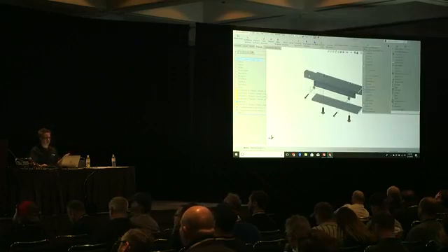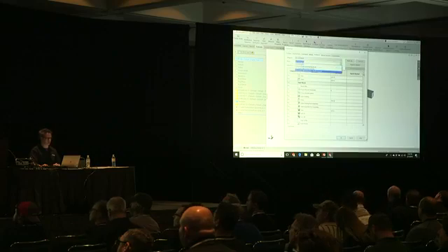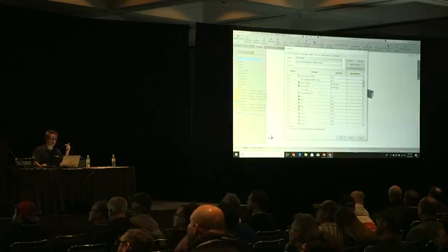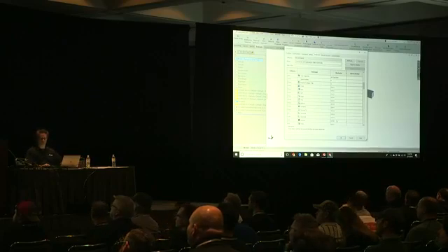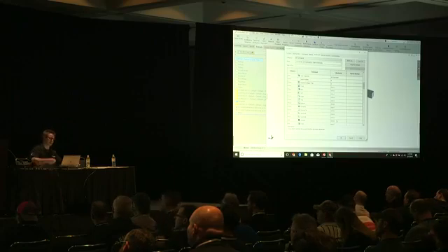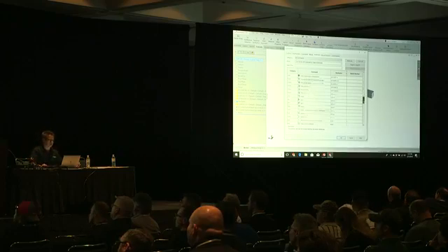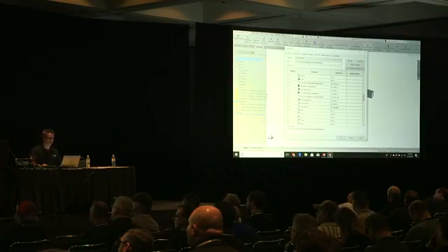So how do I know all these goofy things? If you dip into your keyboard settings, and I just go for keyboard and search shortcuts, hit the shortcut tab at the top, and it'll put them in order. So these are some of my favorites, just the numbers. Those are your views, because usually I'll have a 3D connection controller, and I have one of the buttons mapped to Control. So I can just mash that, 1, 2, 3, 4. It's front, back, left, right, top, bottom, ISO, normal to. You get into here, you get more of your complex ones. That was the temporarily hidden faces, Control-Shift-Alt. Just jump in, print the list, go through it. I won't bore you with it.